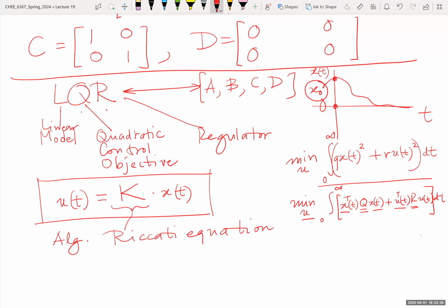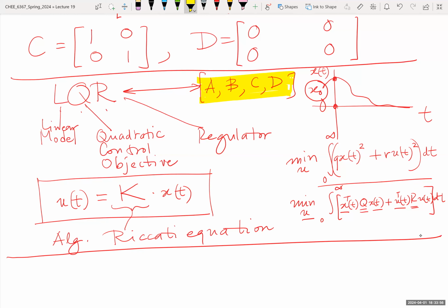That's another equation that has been studied to the umpteenth degree, and we know pretty much all its secrets, how to get it solved and all that with software. And we'll come back to this when we deal with MPC. But I mentioned it early because there is a connection with state space representations. A state space representation, if I know the A, B, C, D, is a natural description of my system, so I can get the linear quadratic regulator for that system.